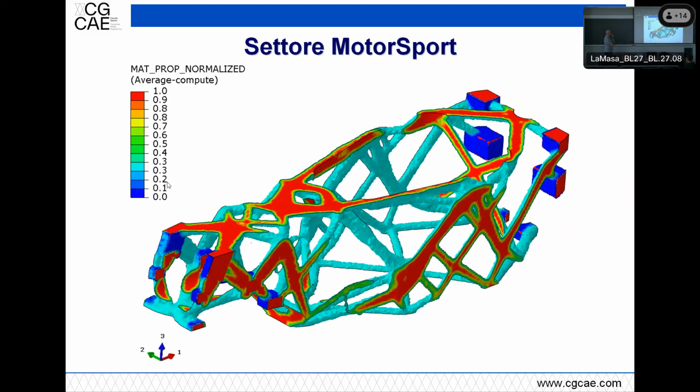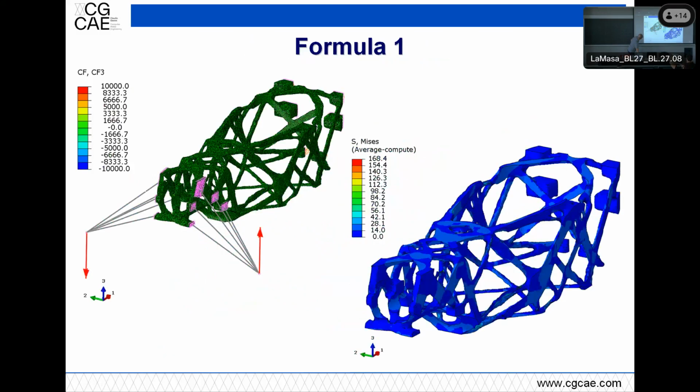So the topological optimizer would tell you that you have to do a monocoque like it was done before carbon, in the 60s, 70s, like a tubular frame in the end, which is interesting on one side. Then, of course, you extract what the topological optimizer is telling you, you reapply the loads, you check for stiffness and stresses, and then clearly this structure needs a good designer to be designed and produced.